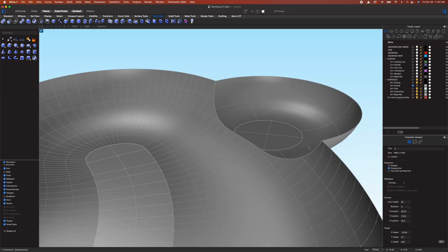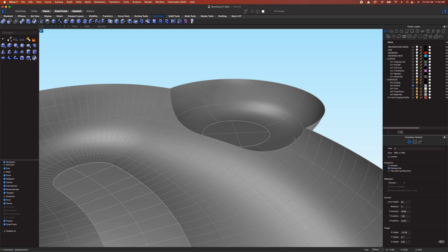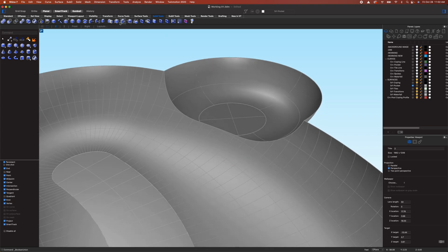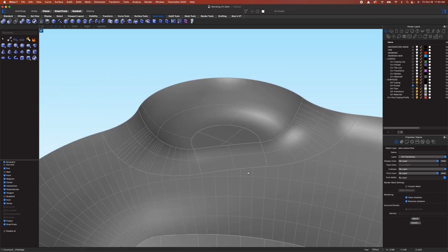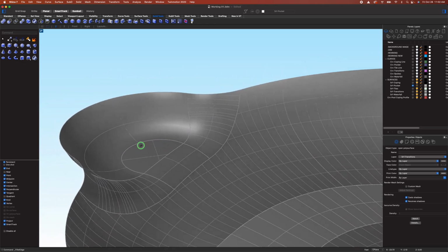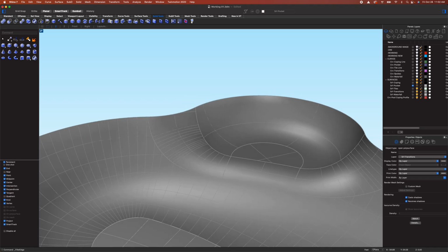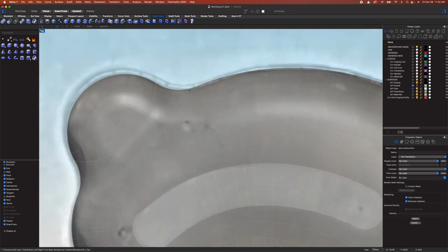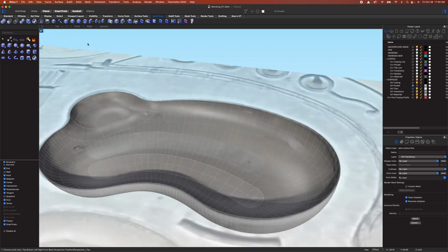But in real life, we would never have a hard edge like this on that seam. Instead, we would have a nice waterfall and a rollover. So let's go ahead and do that. Let's go to our solid tools here, and we'll click on FilletEdge, and we'll select these edges. And 6 foot is probably a pretty good radius. Look at that, did a nice job. But let's see how it looks compared to the satellite image. It's pretty close. I think we probably could have made the bowl slightly bigger in the end, but for what we're doing right here, I'm pretty happy with it.